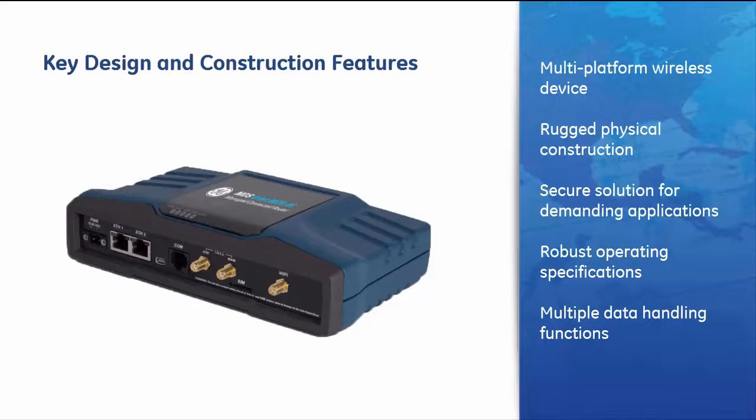It is able to use one wireless method as the primary communication link and then switch to a backup means in the event of an outage. For example, 900 MHz might be used as the primary wireless interface for a field monitoring application, but the 3G or 4G cellular platform could be configured to carry traffic in the event of a communication problem.